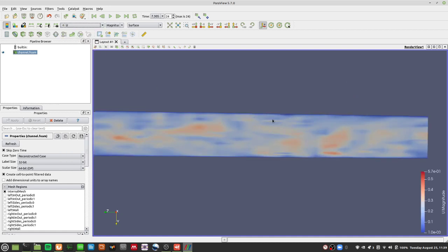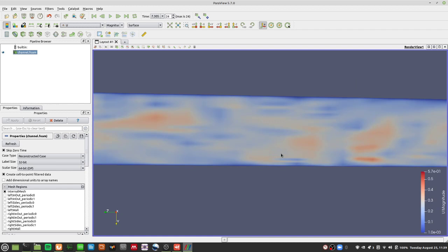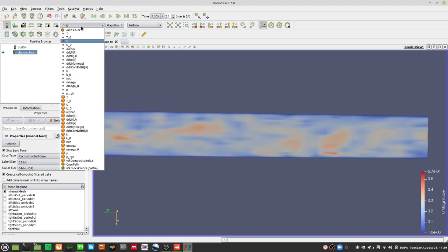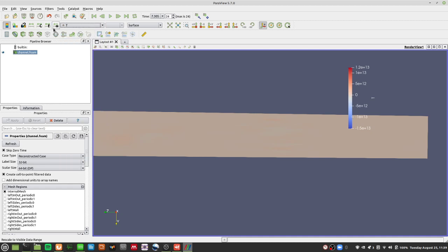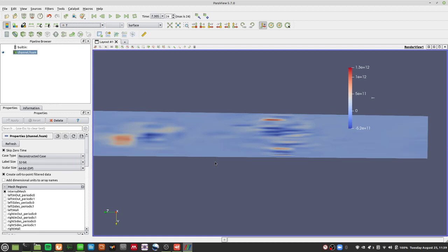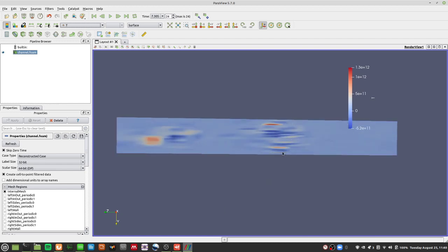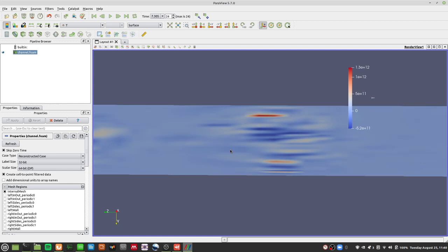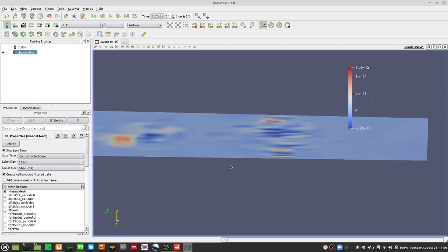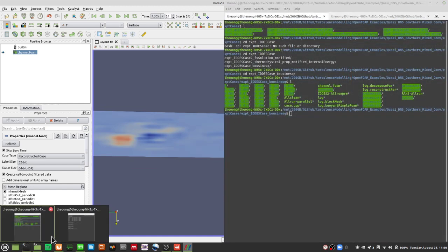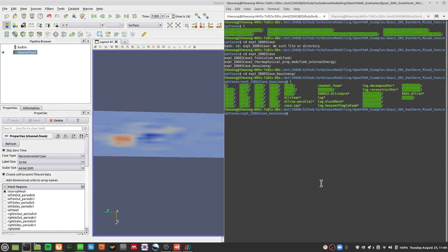However, the velocity profile is still pretty reasonable, as you can see here, but it is not functioning the way it should be. There are numerical instabilities, and normally buoyantPimpleFoam would crash if the temperature goes below 0 Kelvin. buoyantBoussinesqPimpleFoam doesn't do that. It will keep solving and solving, but you can consider this case sort of failed. But hey, it shows you that the differences in algorithm make a huge difference in how you get results.